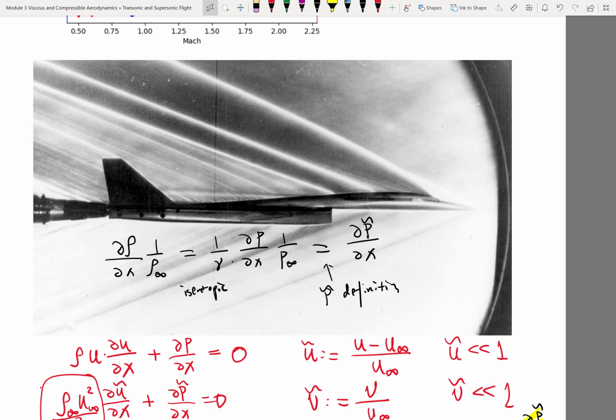The nature of elliptic partial differential equations is represented by the most commonly known one, Poisson's equation. That's the same equation we had in incompressible flow, where we wrote the divergence-free condition for velocities and said that the velocity is equal to the gradient of the velocity potential, right?